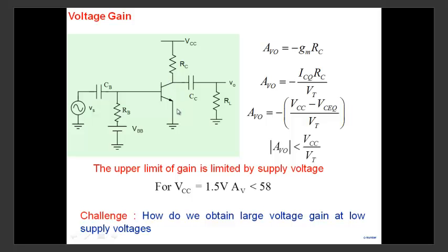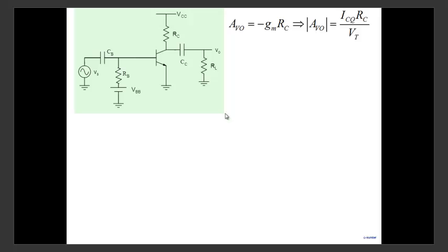So when you look at the emitter as an input and the collector as an output, is there a gain between emitter and collector? What is the relationship between emitter current and collector current? Less than 1. Gain is less than 1. So when I use my input as the emitter and output as the collector, I'm actually operating with a current gain between input and output which is less than 1, and it works as an amplifier. Current gain, as you see here, is not essential to amplification. But that's what I'm raising. Is beta important? So let's look at that. Beta is very important. But let's see how.